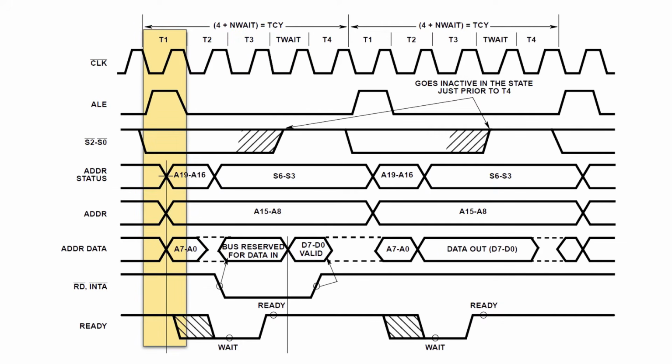During the first of the 4 clock cycles, the CPU asserts all 20 bits of the address, and the ALE signal becomes active for the latches to store the multiplexed address lines states for the rest of the whole transfer. Then, during the second cycle, the multiplexed address and data lines become the data lines, and they are inputs or outputs depending on the data direction.